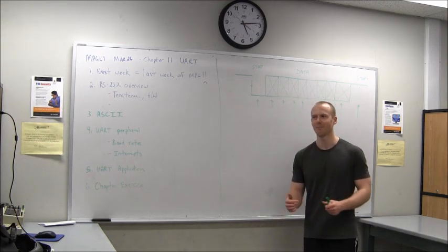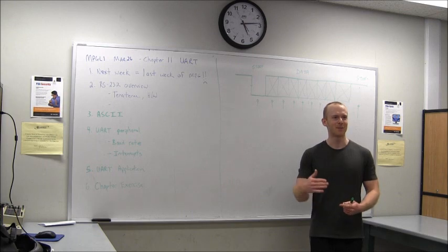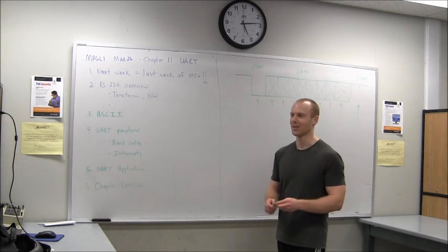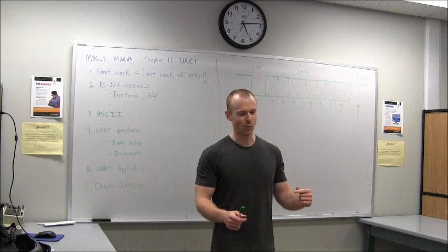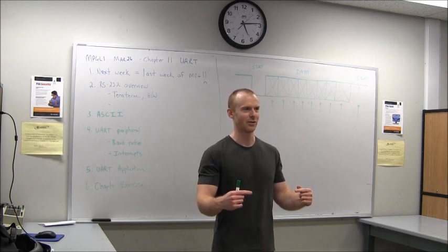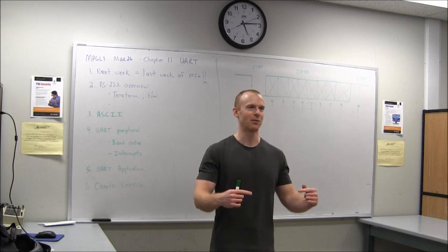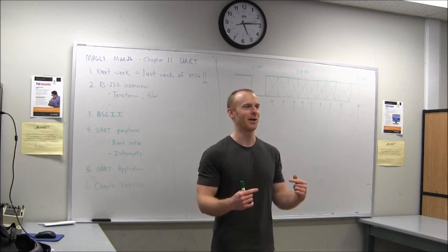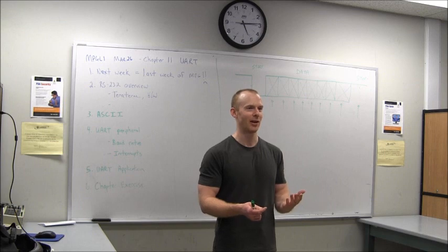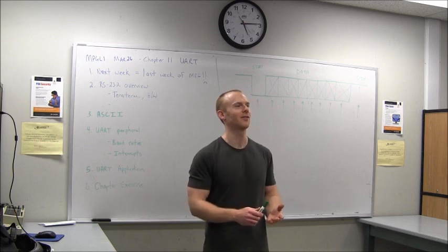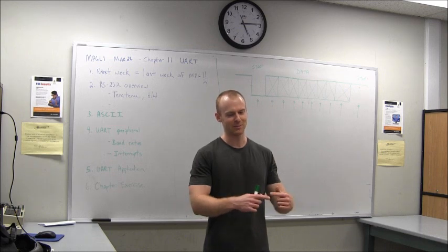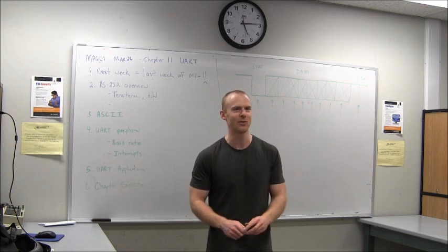Be careful when you're hooking up transmit and receive lines, because sometimes you get a bit mixed up. You'll come across situations where the transmit line from one device will hook up to the transmit line on another device, but somewhere else the transmit line will hook up to the receive line. And it just depends on the perspective that they've decided to name their pins. And I have had to redo boards because I wasn't careful enough in making sure where transmit goes and where receive actually goes. So be careful with that.